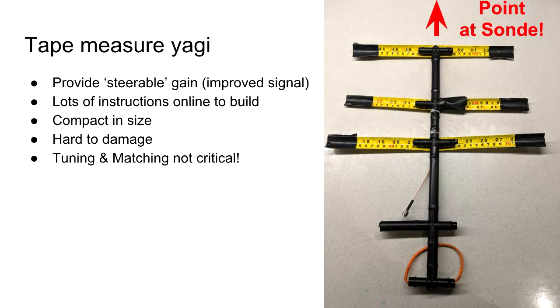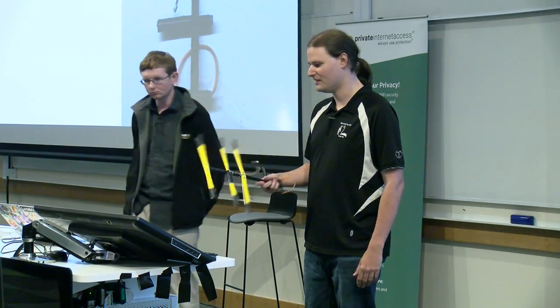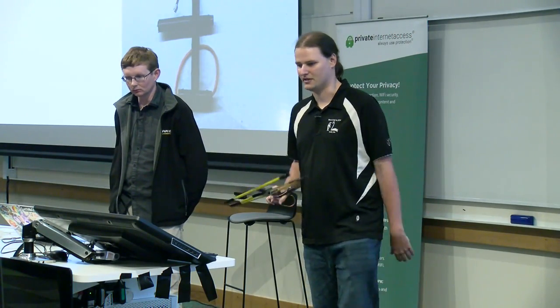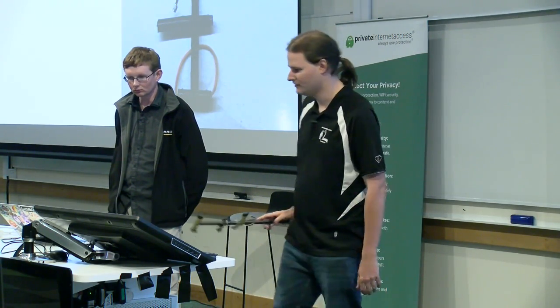The reason why we need this is if the Radiosonde was to land in a field or somewhere like that, you sort of need to direction find to it, because the GPS position you might get is still probably going to be a couple of meters off. And if it lands in a field, you're not really going to see the Radiosonde until you step on it. So you pair this up with a radio and you swipe around until you find the strongest signal. There are some basic direction finding tips, like the signal might be behind you, so make sure you keep that in mind.